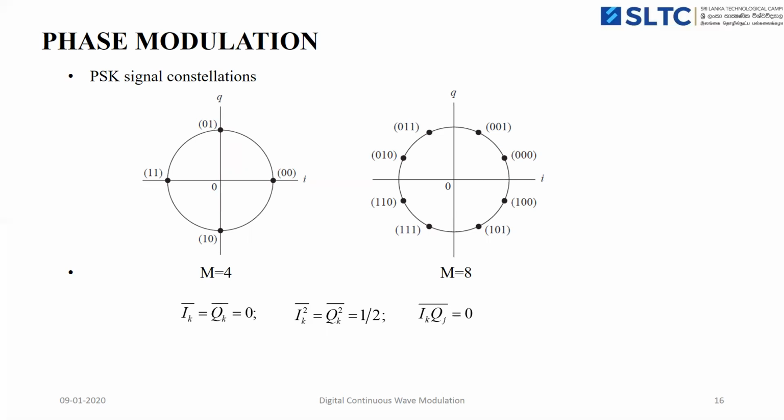So this waveform shows the phase modulation constellation diagram for two different modulations, 4 PSK modulation and 8 PSK modulation. In 4 PSK modulation, there are four symbols present, and we can see these four symbols located in four different phases: 0, 90, 180, and 270, and so on. The amplitude of this PSK is constant. Only the phase changes.